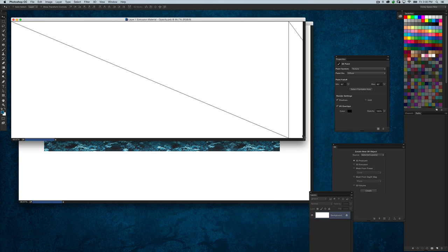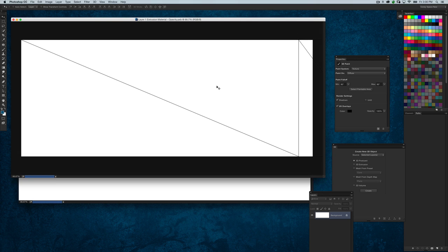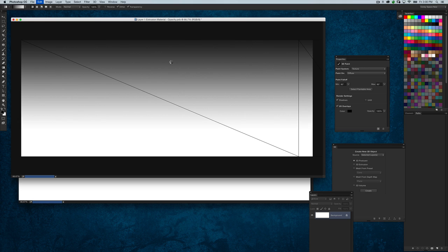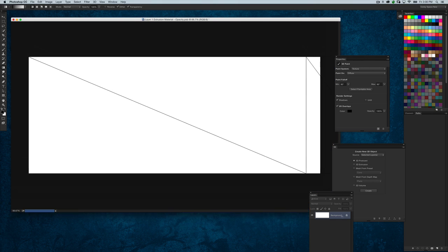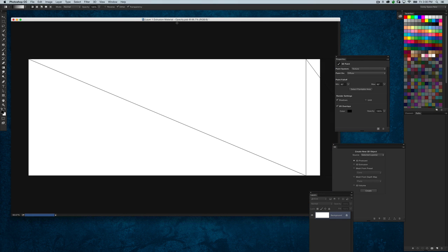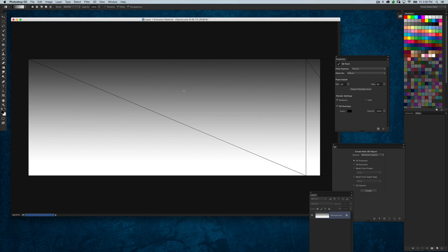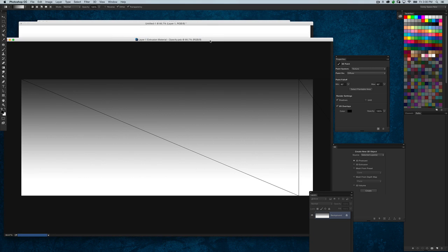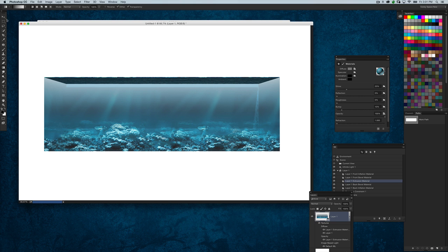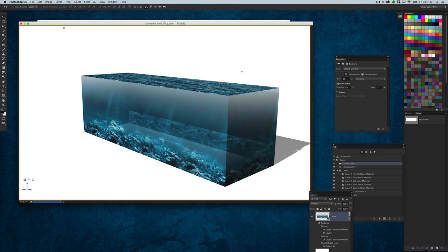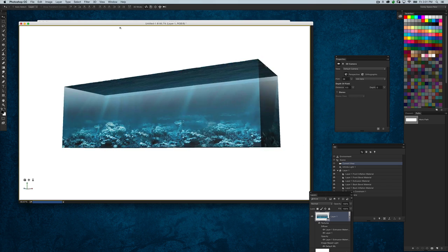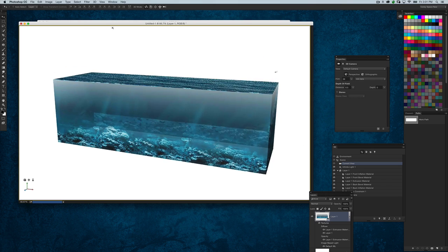And this is essentially a layer mask as a texture map. And all I'm going to do is add a simple gradient coming from the top, just a simple kind of gray gradient. I'm actually using black, but I'm starting the gradient far outside the image boundaries here, just dragging it down so it becomes more gray up here in the actual visible area. Now when I save it and close it, notice now we have the transparency. We can actually see inside of the box there, and we're getting that cool transparency on the water.